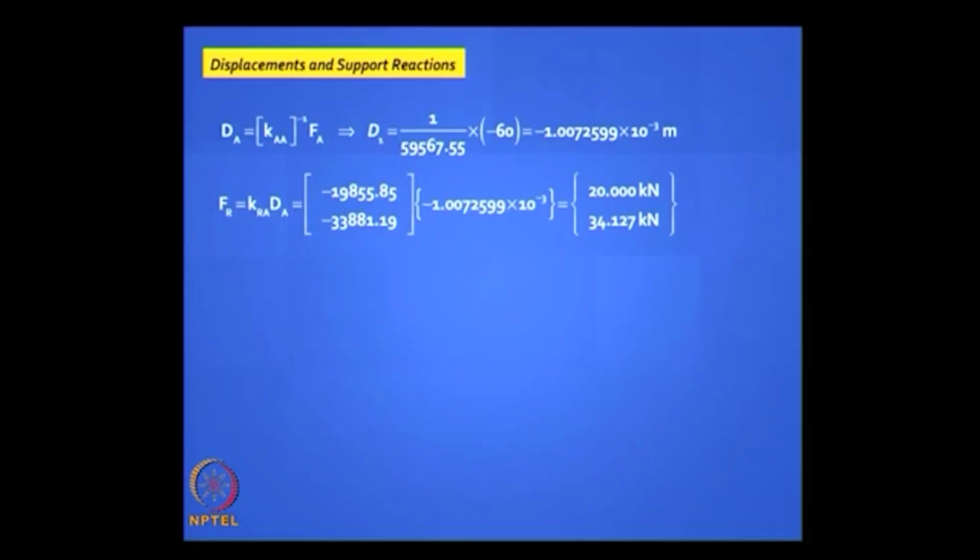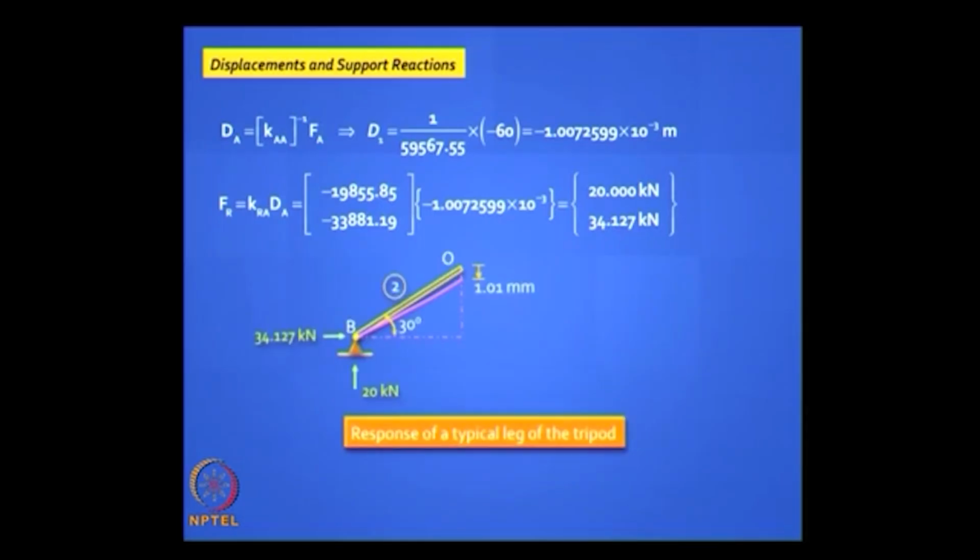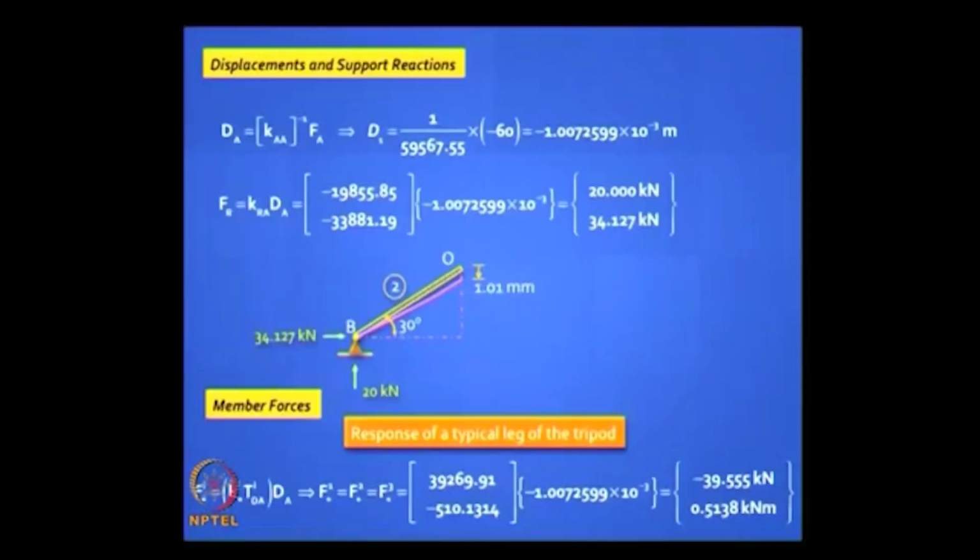Look at the answer you are getting. Vertical reaction will always be 20, because 3 times 20 must add up to 60, no question about that, but your axial force need not be 40. You will find that the joint goes down by 1 mm, which is realistic, and you can calculate the internal forces.